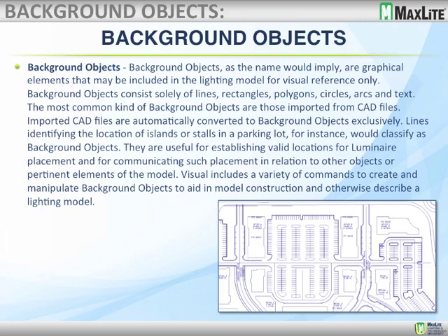Otherwise, if there are no dimensions and it just says scale 1 inch equals 20 feet, and there's no physical drawing line saying 20 feet long, we have to go in and figure out a door opening or a parking stall, a door opening being 3 feet wide. So we have to measure from that. So that small area is what we have to scale. It could be off just a hair for that small bit, and it throws the whole drawing off, where we may end up with an extra fixture or not. So by all means, please get us as much detail as possible. That helps out. Great point.